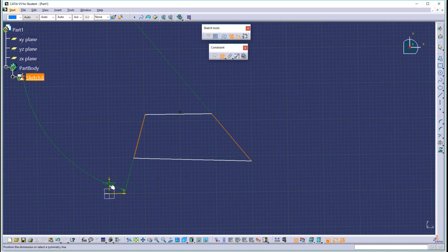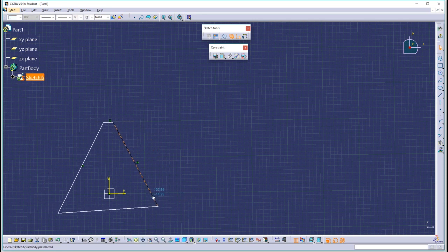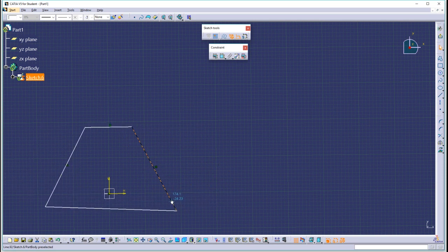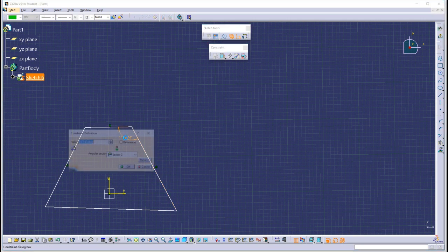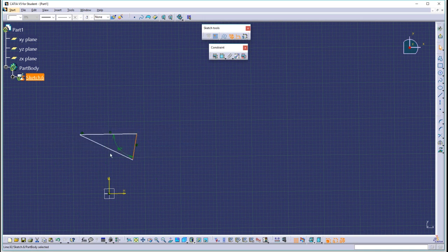If I pick this axis right here, now it's used that axis line as a symmetry line for the two, and they both have the same angle now, and if I push one towards the origin or pull it away from the origin, they both move the same. And in fact, if I put an angle on here between this one and this one, and I change this angle from 117 to say 80, they both change by the same angle.